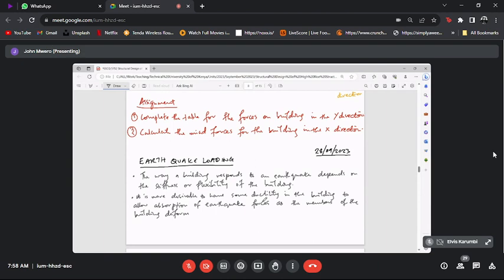And that vibration is a function of the mass of the system. You remember lumped masses? So you'd have maybe a single mass or multiple masses, multiple degrees of freedom. It depends on the mass, and it depends on the stiffness of the springs that are supporting these masses, from your dynamics of structures.